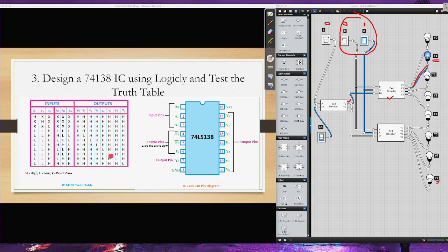So this is actually an active low IC. Okay, because this is a real IC, meaning to say the outputs are active low. Of course, there are also ICs whose outputs are active high, but this one is an active low IC. That is why, in our previous discussion, we designed a 2 by 4 active low decoder.